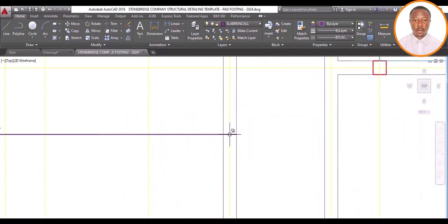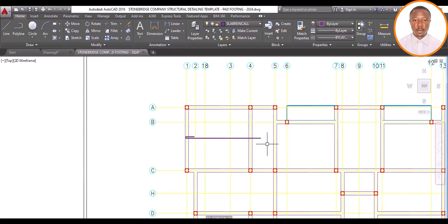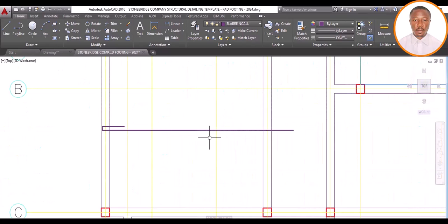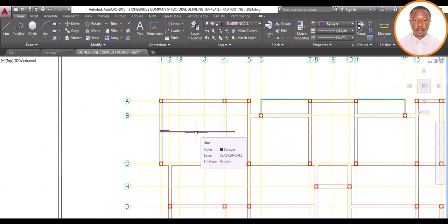Now I'm coming here. All I need to do, because definitely I will not stop here, my reinforcements have to enter the next slab by 600, which is my lapping. So I enter 600. So that is that. And coming to this other aspect again, I'm done with this slab for this x-axis. For this direction, I'm done with this slab.